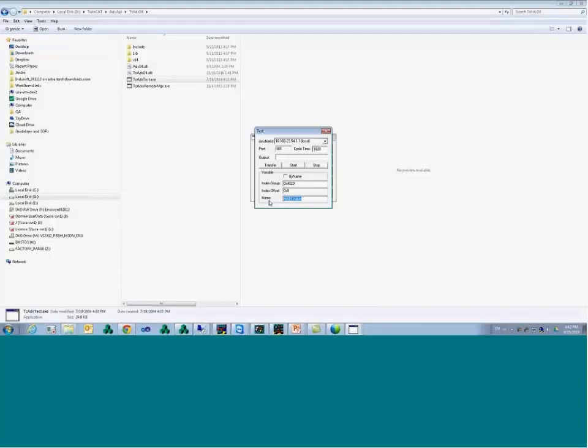Okay, so the question is, why are function block parameters not accessible on TwinCAT 3? That would be more a question that we would ask Beckhoff, if there is any special configuration. It's not a limitation of the driver. The driver is going to send whatever syntax I have to send to the ADS. Okay? So I highly recommend whenever you see something weird, go and test using the test program here. That's going to be under the ADS API, TC ADS DLL.